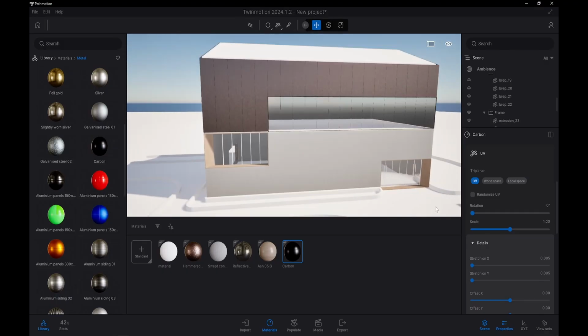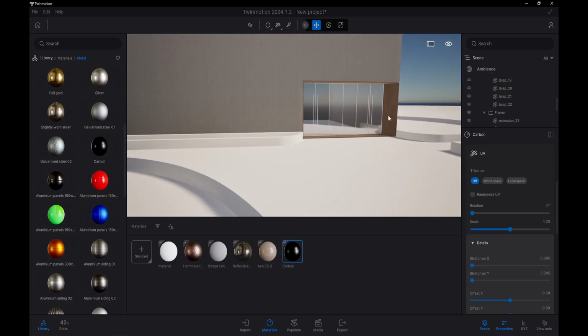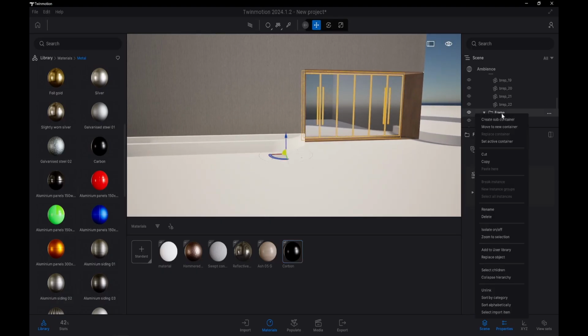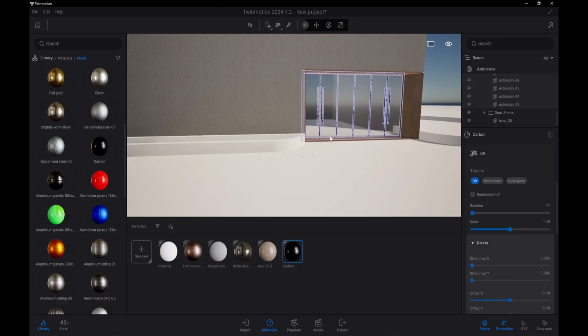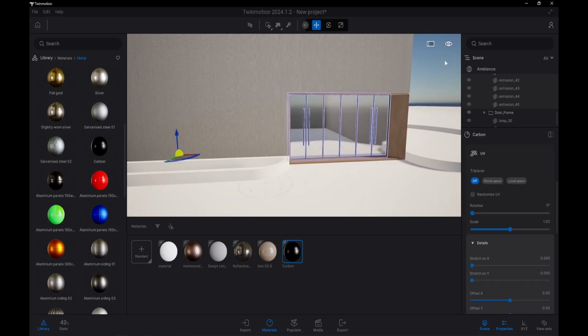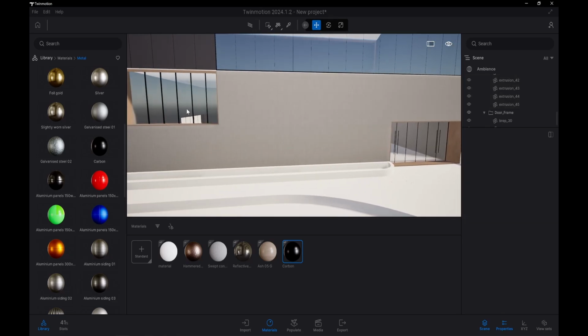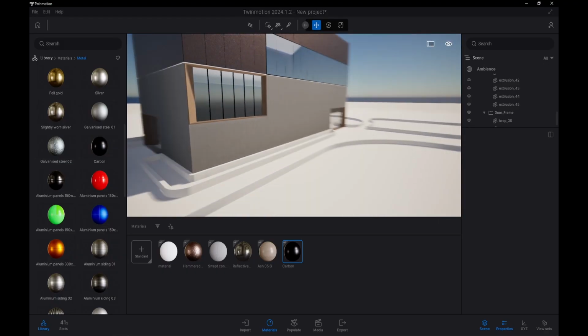And same thing here. These are, I think, the window frames. Yeah, there we go. So let me do select children and apply by selection. We click on carbon from there like that. Click outside of it, and there you go. You see? I got them there and there. Remember, this was the actual responsible way of doing the frames. The other one isn't.